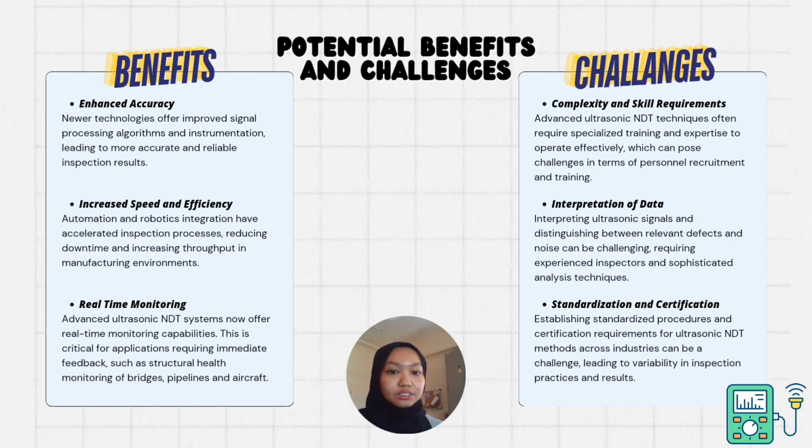Second, interpretation of data. Interpreting ultrasonic signals and distinguishing between relevant defects and noise can be challenging, requiring experienced inspectors and sophisticated analysis techniques. So the last challenge is standardization and certification. Establishing standardized procedures and certification requirements for ultrasonic NDT methods across industries can be a challenge, leading to variability in inspection practices and results.